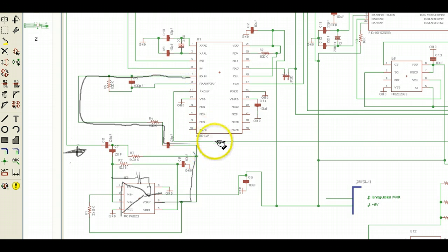And this is an MX614, and you can look up the data sheet online. So tones come in here, 1200 and 2200 Hz tones, and this chip will convert those tones into DC levels, and I'm looking for the DC level, and I'm having a little trouble finding it. It's one of these signals over here that goes to the PIC, and I believe it is RxD right here.